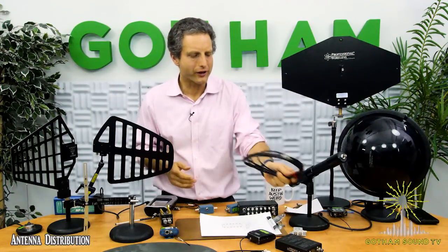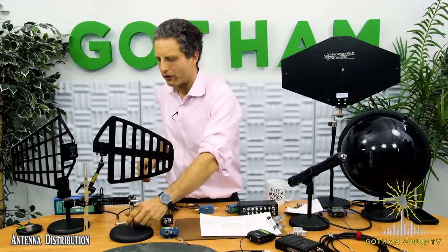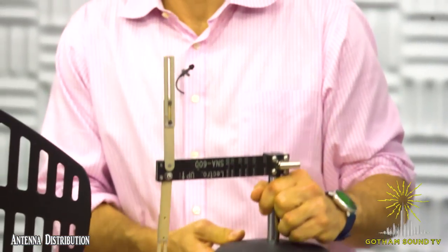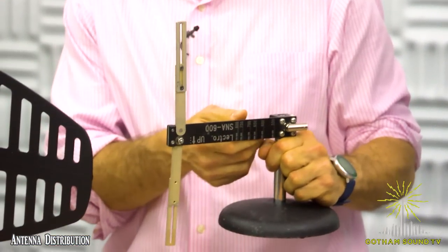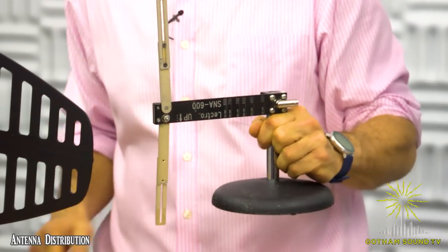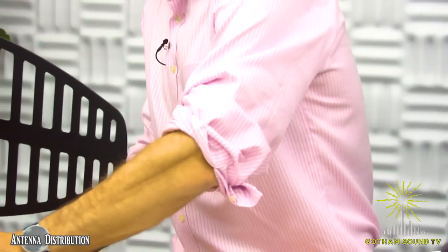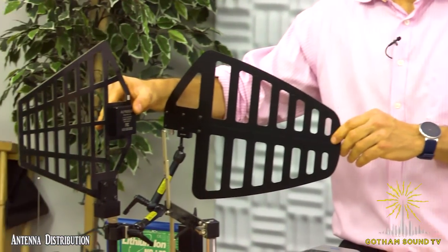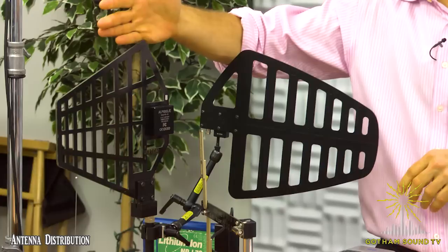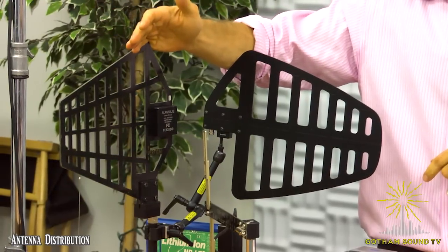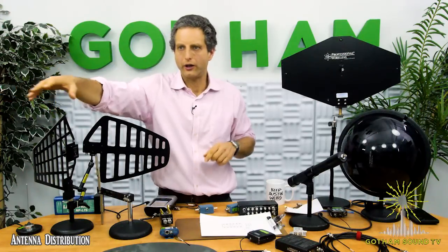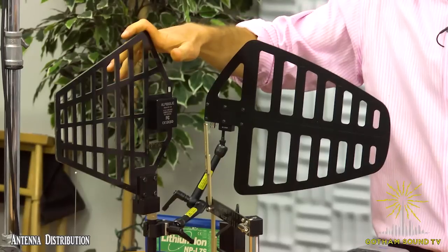What you need is an antenna with some kind of built-in ground plane. And that's where things like the SNA antenna come in handy. Yep. So that's what this is, or a folding dipole. It's also where these shark fins come in handy. They have directionality, and you can also use that directionality to your advantage. They're sensitive in the front. They have gain in the front. They have rejection along the sides.